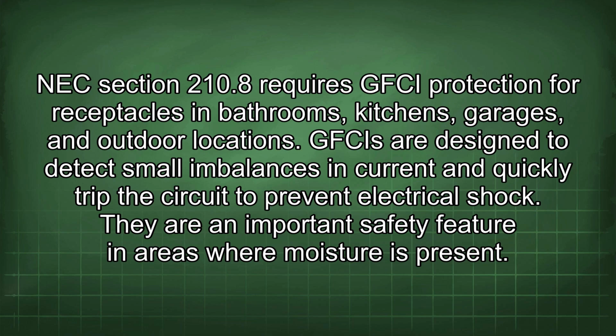NEC Section 210.8 requires GFCI protection for receptacles in bathrooms, kitchens, garages, and outdoor locations. GFCIs are designed to detect small imbalances in current and quickly trip the circuit to prevent electrical shock. They are an important safety feature in areas where moisture is present.